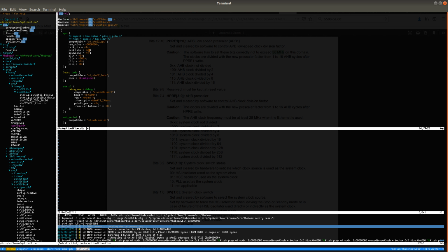So now we'll have H clock. So I wonder if the value is correct for P clock 1, because when I was dividing the H clock to bring down to 50, then this value should also be derived probably from the system clock and not H clock, which means that we can keep that at 2, so that we still should get 50 megahertz there.